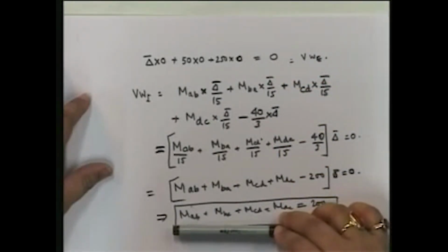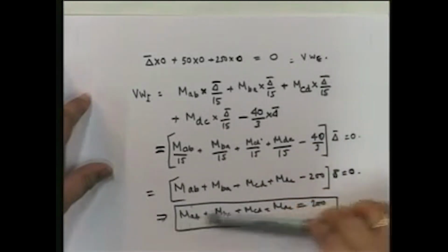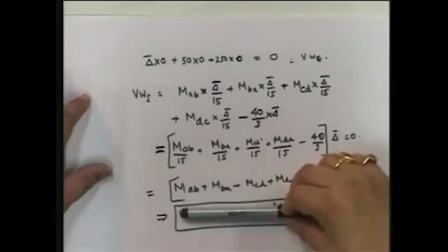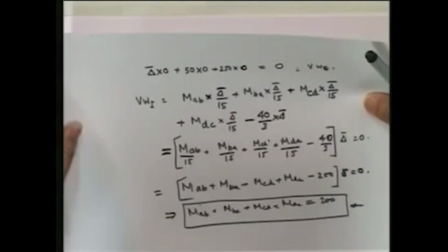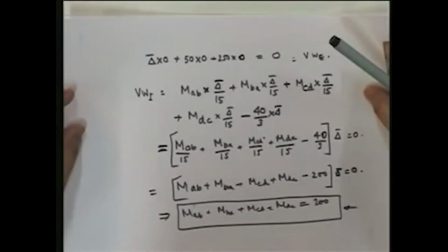Note that this equation is actually really a virtual work equation. Okay, it's a work equation. Only thing is that it gives you something which looks like a moment equilibrium equation. And these three, which you solve simultaneously, you will get theta B, theta C, and delta. So much for all of this, and you will see that this equation is identical to what we had got last time. Okay. Now here, this is the concept of the application of the principle of virtual displacement.